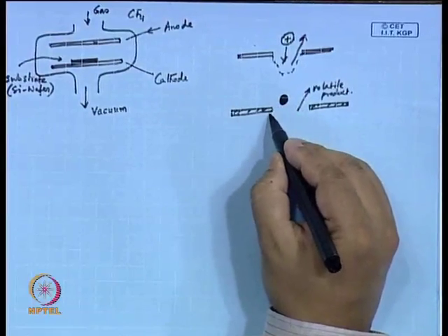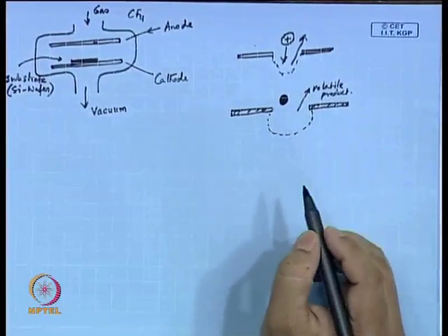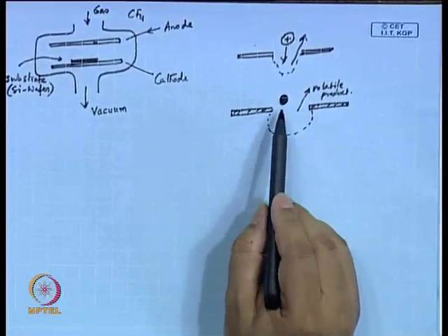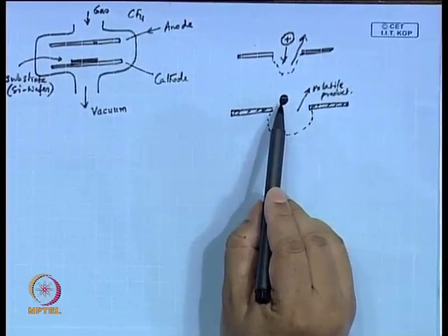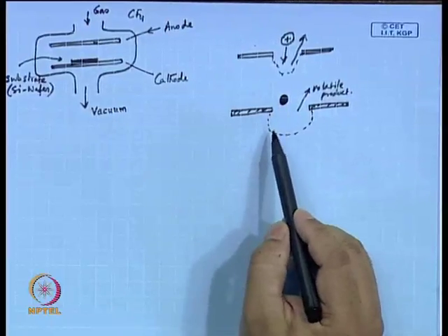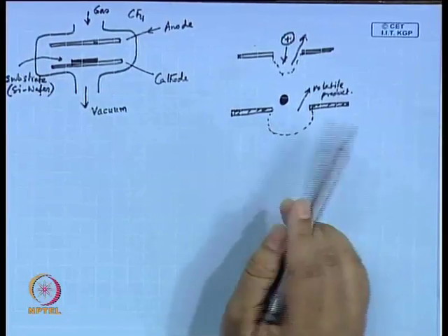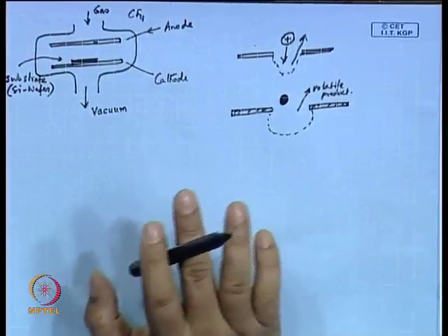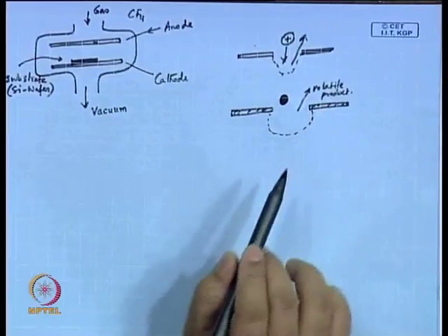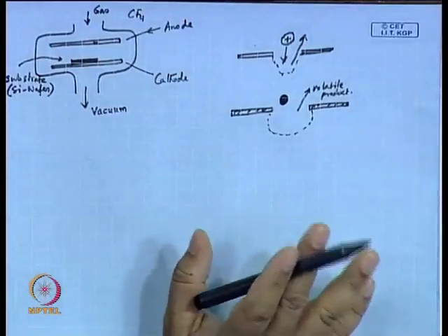So, what you expect is isotropic etching happening, because the movement of this XeF2 molecule into the groove is purely controlled by diffusion, and diffusion should be isotropic in all directions. It does not have any preference. It is not that it is bombarded and then reflecting, and the angle of inclination matters. That is not the way. It is simply diffusing in a very gentle mode, and then it is going and accessing the silicon surface, having the reaction, and once the reaction is done, the product itself is volatile.